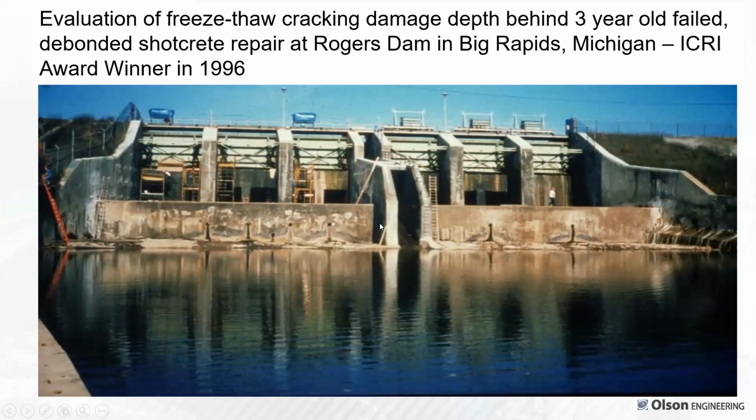The problems were, and let's just talk about the old style dam for a second. These are tainter gates, as many of you know. Here are the abutments, the piers, the weir, some interior rooms underneath it, and most may not know what this is. The best guess is it's a fish ladder, but in 1910 we weren't so worried about fish. It actually was designed as a log chute, so the logs floating down the river could go off towards the sawmills to help build Chicago. So that's basically the old dam.